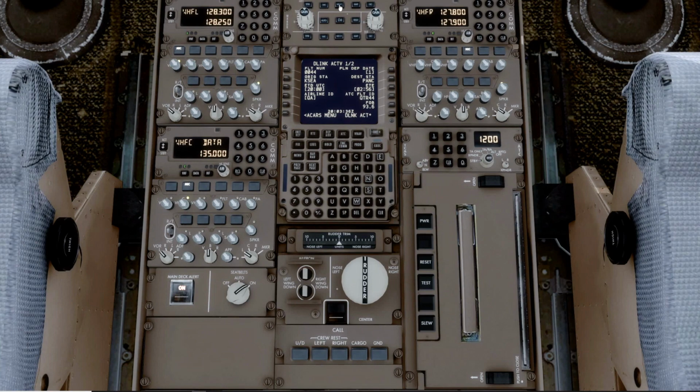Radar panel, weather radar, make sure it's in weather turbulence, and left or right radio. The left I think is, the right is pushed down and the left is up, pushed out. Gyro, we'll leave it on left. And rudder trim 0, aileron trim 0, we can check the control column for that. Rudder trim center is a momentary action switch, it's out. No lights. No lights here.